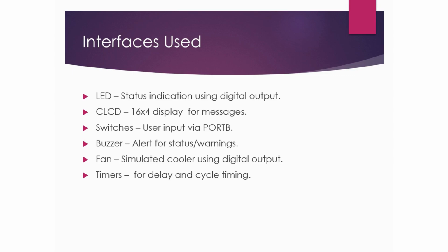LEDs consist of a semiconductor chip mounted on a reflective material and then encapsulated in a transparent lens to protect the chip and focus the light. The semiconductor chip is typically made of gallium arsenide, gallium phosphide, or gallium nitride, which determines the color of the emitted light.